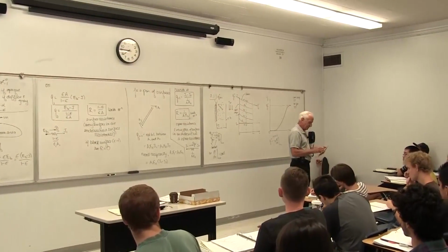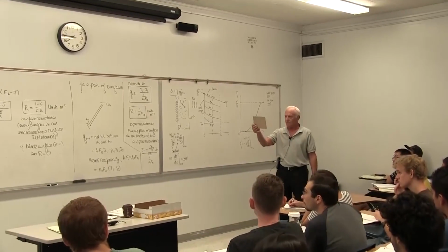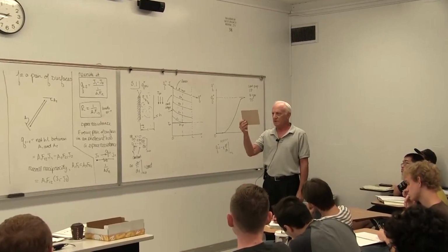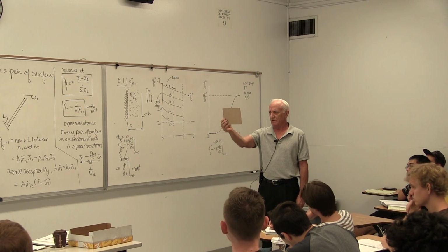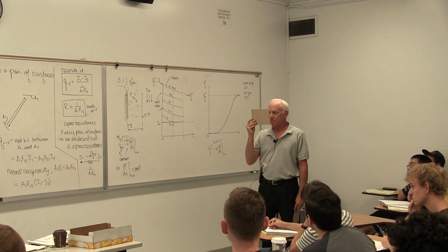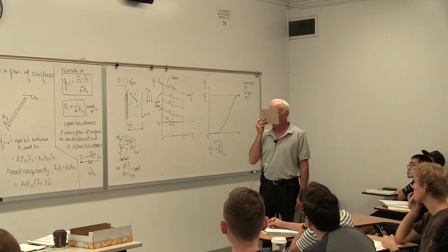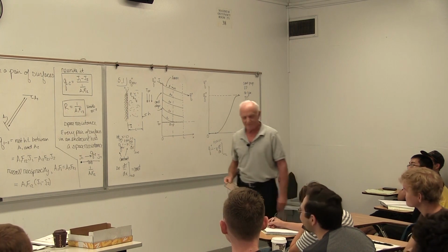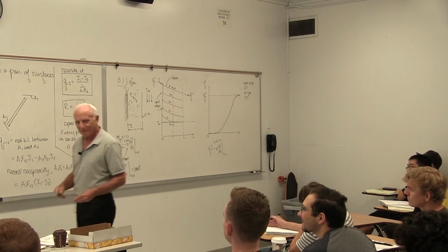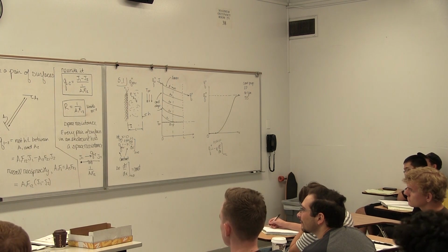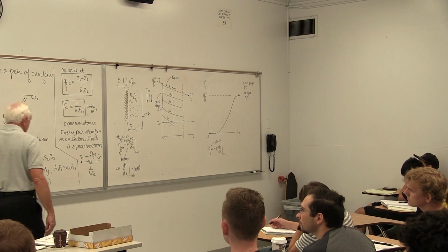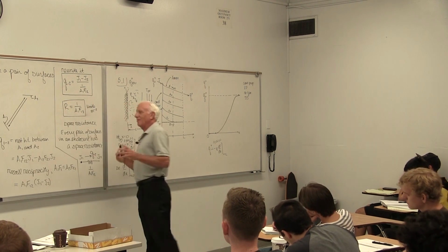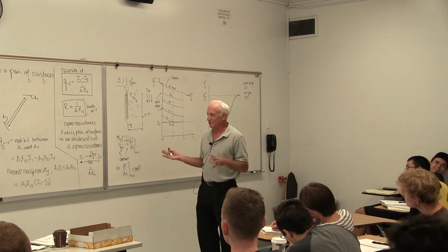And why is it called view factor? Well, it's what I see. In my field of vision right now, that's probably 20% of my field of vision. That's probably 0.5 right there. And that's close to 1. That's why it's called a view factor, because our eyes give you some intuitive feel for these F values. Okay, so now we've got all we need to look at an enclosure.